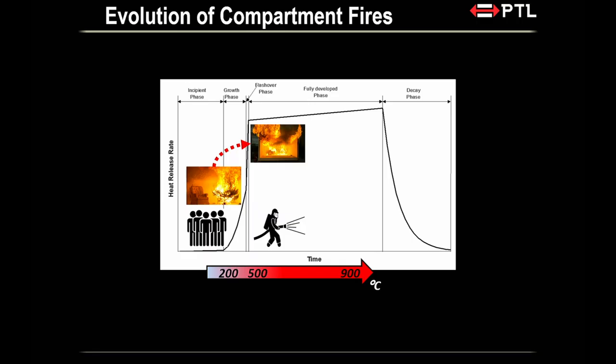And you wonder why 900 degrees Celsius? That's the temperature of what we call a diffusion flame. Diffusion flame is where the fuel molecule will need to travel to meet an oxygen. And this is more or less the scenario that we have whenever we have accidental fire. We don't deal with what we call pre-mix, which is the flame you use for cooking, where the fuel and oxygen are all well mixed and you have a blue flame. We don't deal with that kind of situation. Our situation is diffusion flame. They're bright, they're yellow, they radiate a lot.